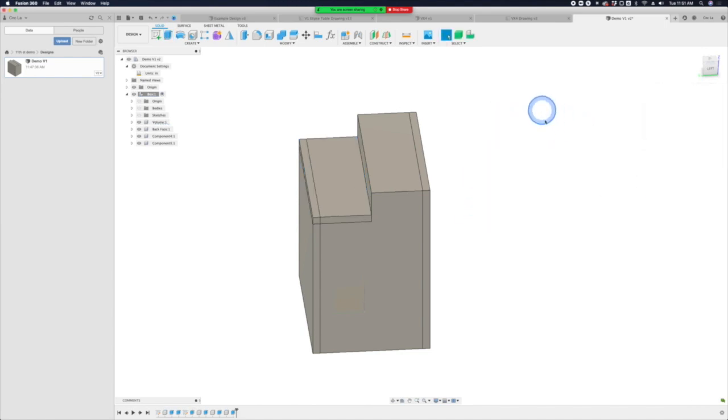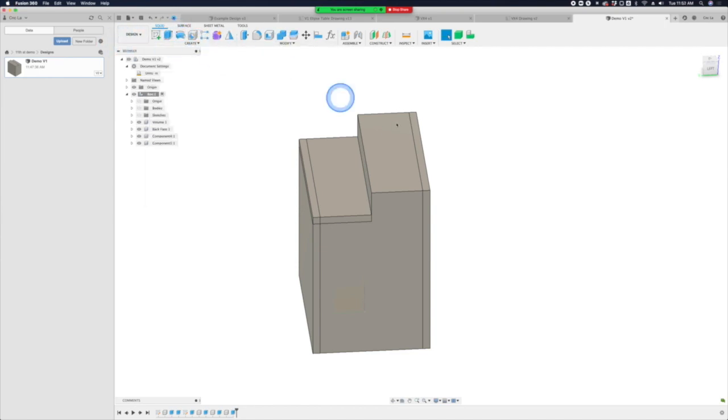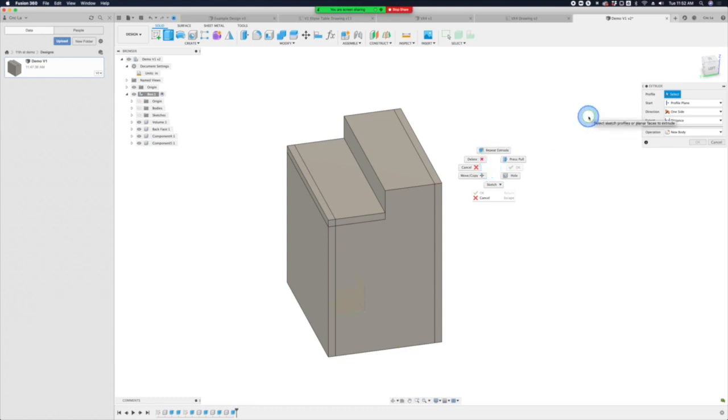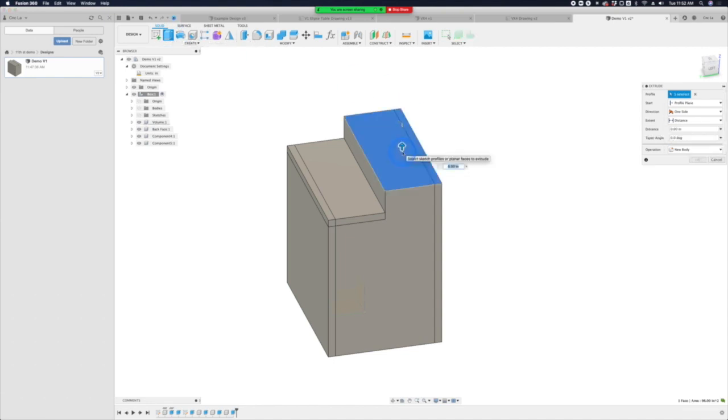Oh, see, I did use that right click. So if you've just done an operation or executed a feature, whatever you want to call it, if you right click and go up, you can repeat extrude. I guess I didn't even realize I was using those. You can get a little faster at doing things, and you can change these defaults to where you just make a quick gesture with the mouse, and then it takes you into the operation you want to do.